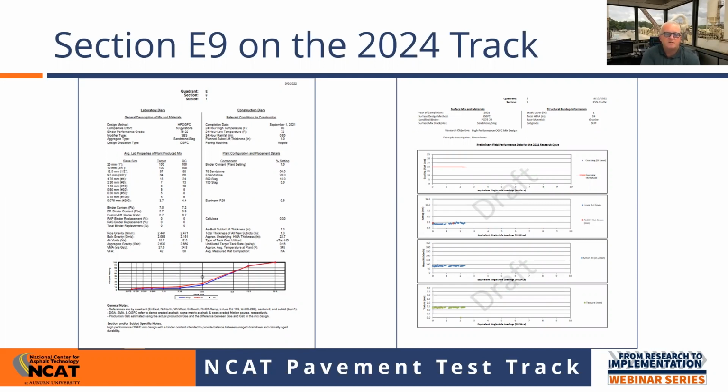If you look at the construction report, it has the design, which I show as the target. In the case of this mix, the target was 3.7% minus 200. When we ran it, it was 4.4. If you look at the gradation curve at the bottom of that page, it ran just slightly finer than it was designed, but it still ran really well.